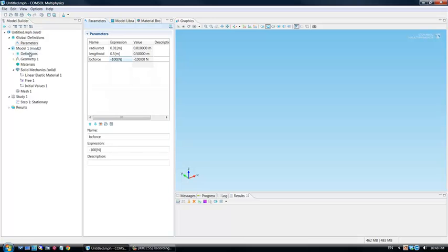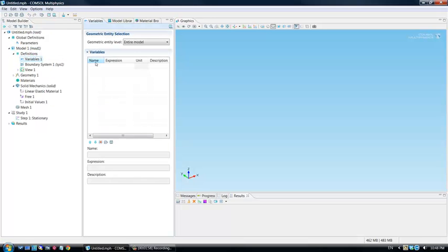Now under model 1, I'll be defining a function, the analytical solution of how much displacement I should expect for a bent rod with an applied force. So I'm going to compare at the end the analytical solution to the numerical solution COMSOL provides. So the equation is 4 times the force times 3 times the length of the rod. I'm sorry, first the name, I'll call it deflect.